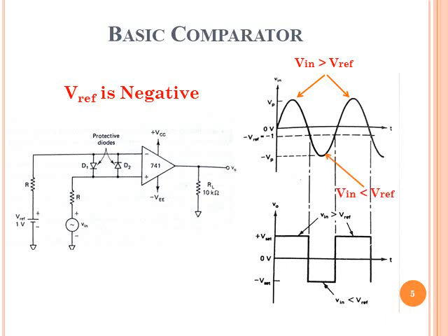And in this case, the input voltage is less than the reference voltage, and since the input voltage is applied on the positive terminal, the output voltage becomes negative. And we have discussed earlier that in each case the output voltage cannot exceed the saturation voltage, plus or minus V saturation.